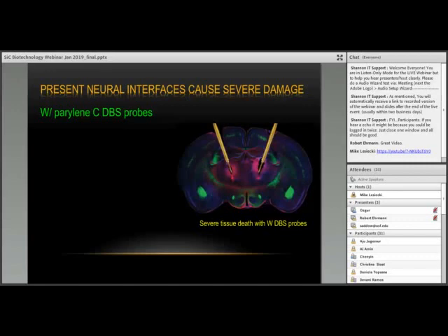So what would happen initially is the probes are put into the brain. The clinician will start to do a regimen of electrostimulation, perhaps at a volt, to give you an idea roughly of the number. Of course, it depends on the power and the current. But let's say they start out at about a volt, and they're able to get neuromodulation that's effective. Over time, due to the interaction of the probe materials with the brain's immune response, fibrous tissue, what's called a glial scar, begins to build. The way to overcome that, let's just increase the juice. We increase the potential. You still get the treatment to work, but eventually it will stop functioning over a longer period of time.